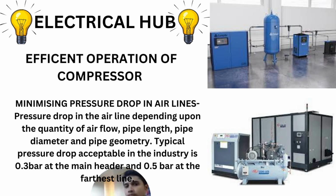Minimizing the pressure drops in the air lines. Pressure drop should be minimized. It depends upon the quantity of the air, length of the pipe, diameter, and its geometry. But in the industry, at the main header, 0.3 bar and at the farthest end, 0.5 bar pressure drop is only acceptable.